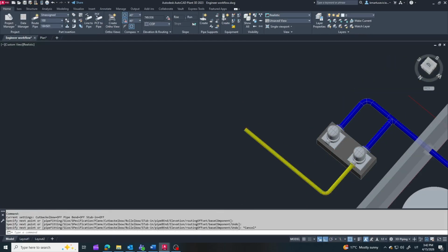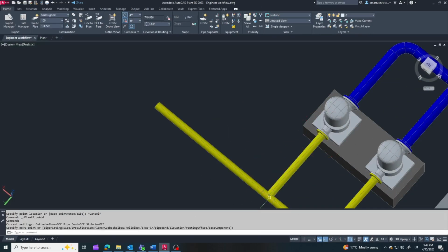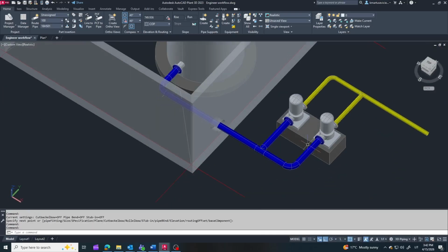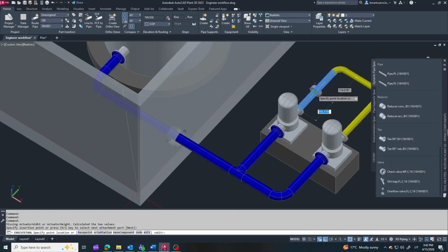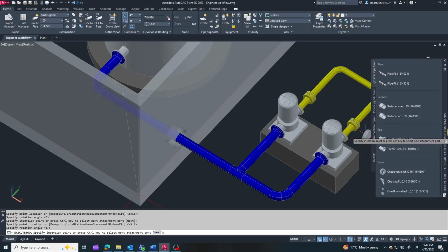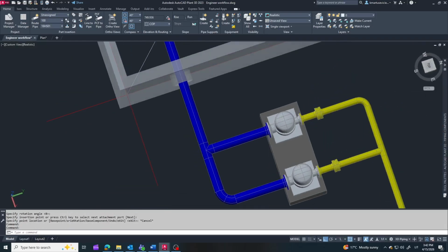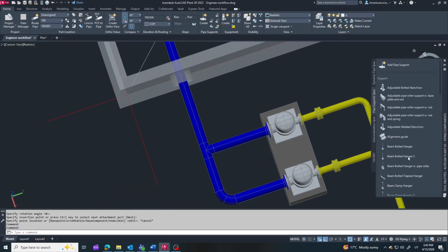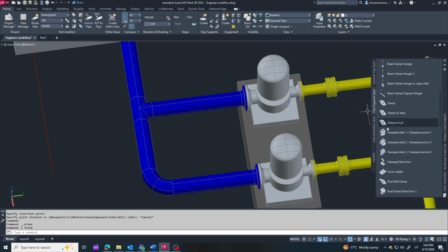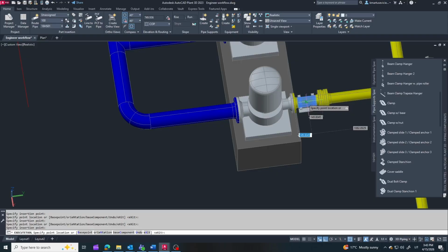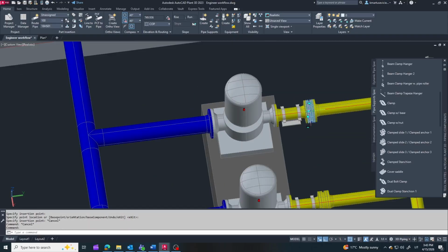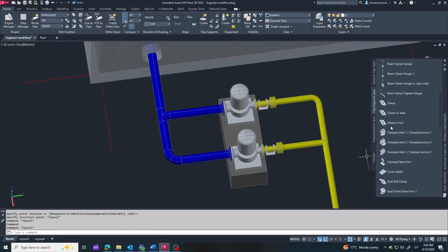One more task for the civil engineers. We need to define pipe supports, metal support structures that carry the weight of piping components and prevent stress on the pipes. For example, large valves like globe valves can be quite heavy. That's why we route the piping and add supports where needed. Supports are especially important near pumps because pumps do not tolerate loads on their nozzles. Heavy components can cause misalignment and damage the pump connections.